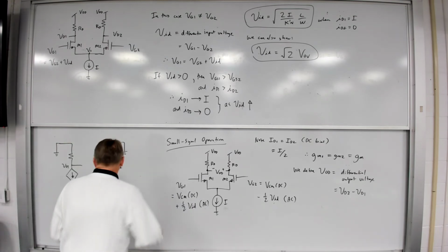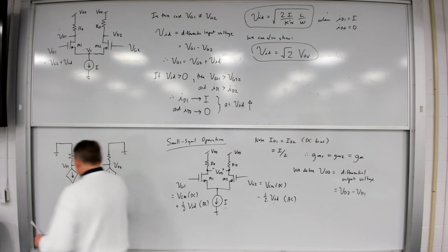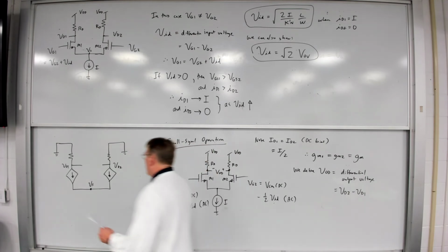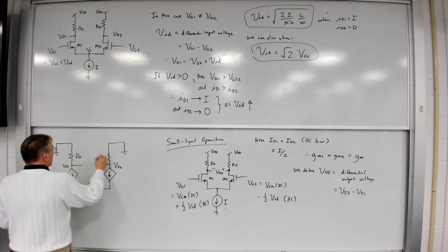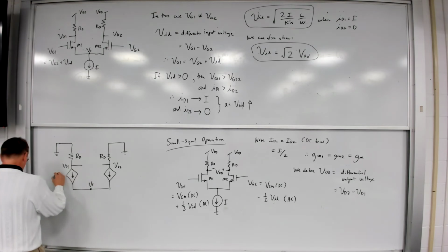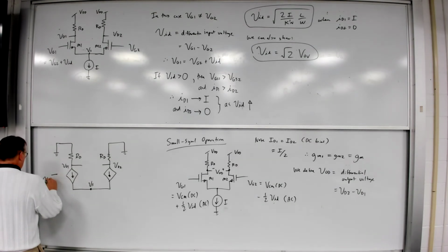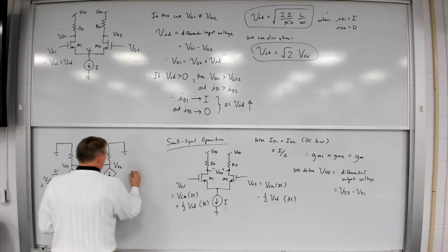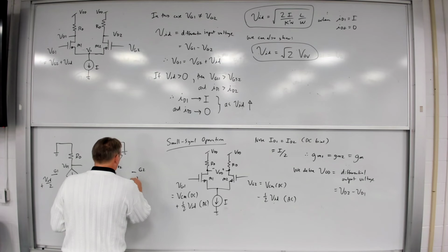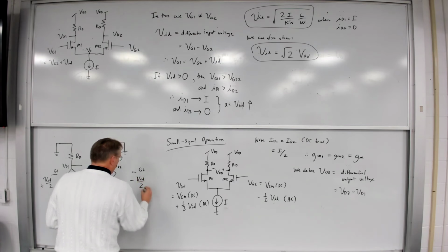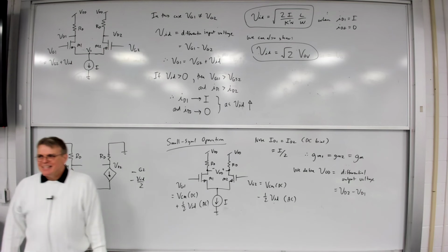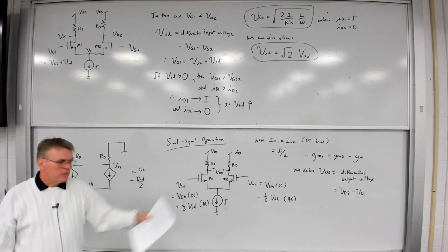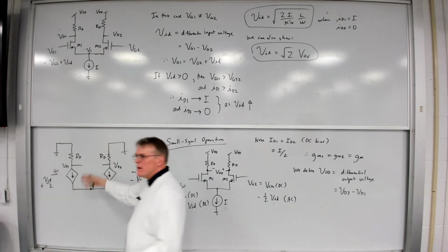Notice the source has nothing connected to it. That's an ideal current source. That becomes an open circuit. Now the common mode voltage, I assume that's DC. I'm zeroing out that DC. The power supplies, I zero those out. And this is all that remains.